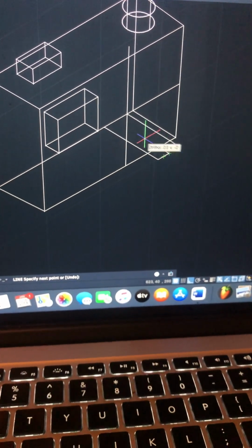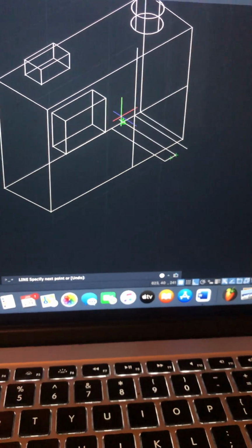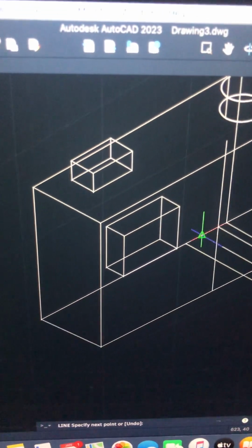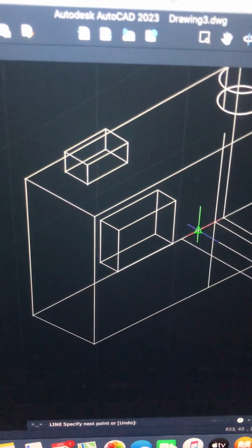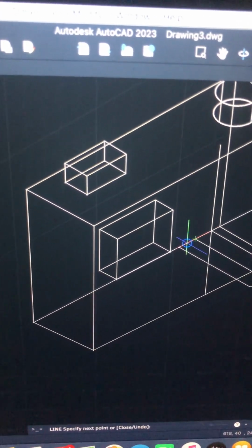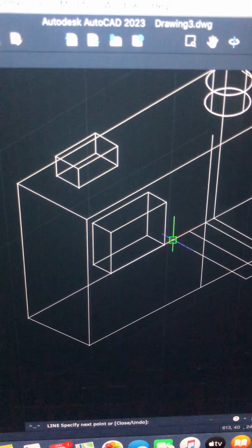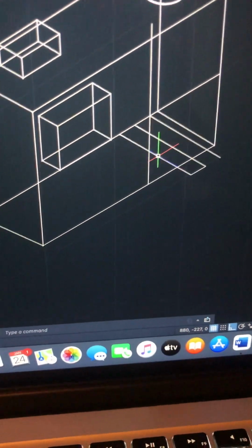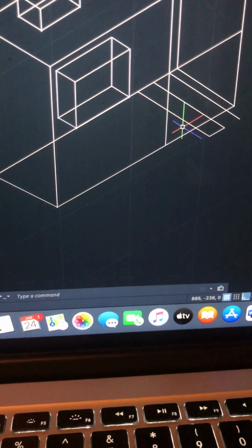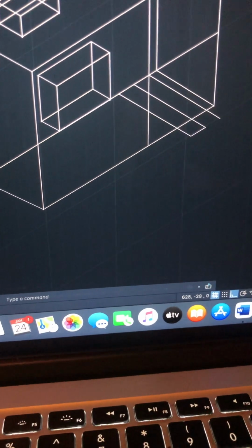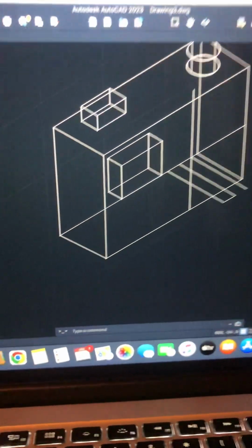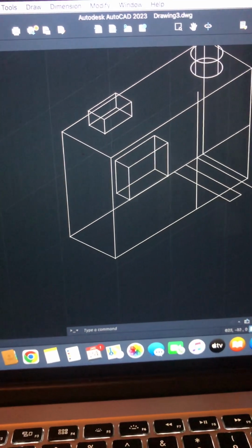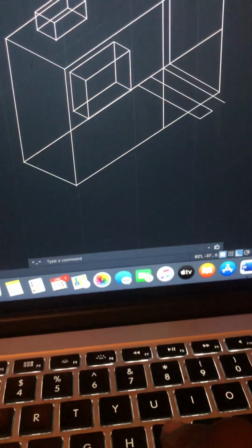So that line, and then we can go back here. And then we can join it, right? It's gonna tell you where to join. And then we can go here and rejoin and escape. So we have a little rectangle here. This is gonna represent the diameter, the thickness of the lens pushing out. So what I'm gonna do now, I'm gonna type join in the command line, J-O-I-N.